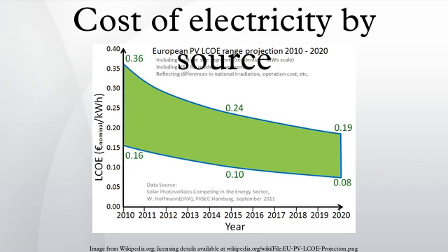To meet peak demand on a system, which only persists for a few hours per year, it is often worth using very cheap to build, but very expensive to operate plant. For example, some large grids also use load shedding coupled with diesel generators at peak or extreme conditions, the very high kilowatt-hour production cost being justified by not having to build other more expensive capacity and a reduction in the otherwise continuous and inefficient use of spinning reserve.